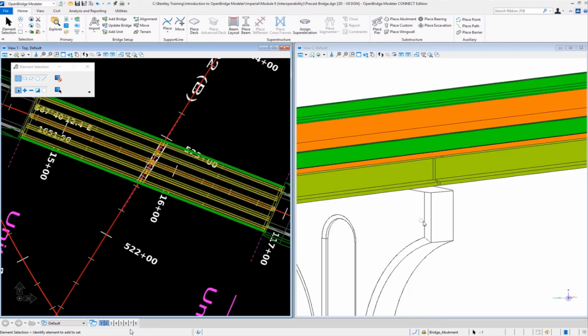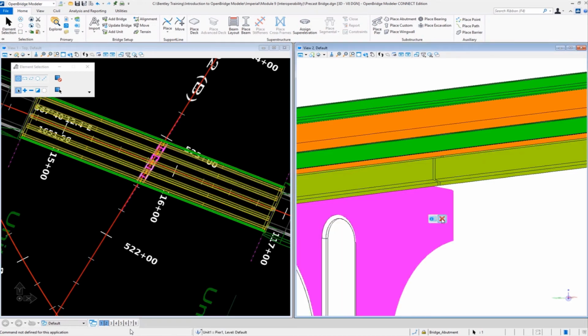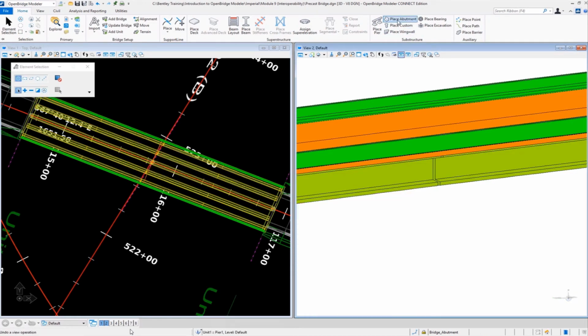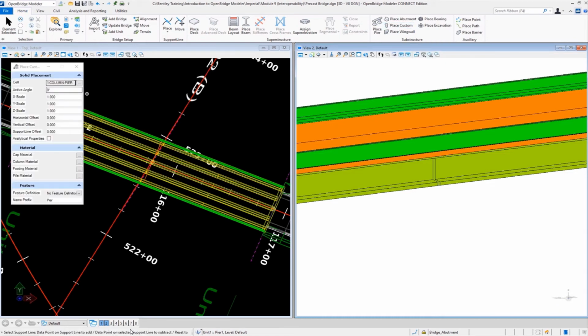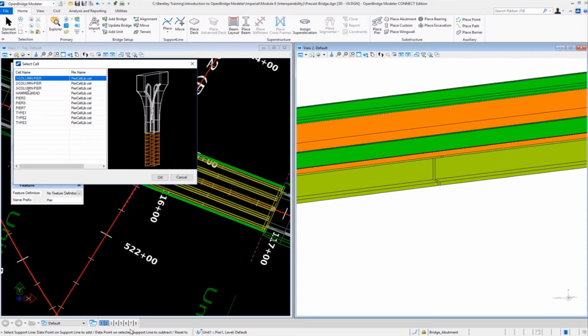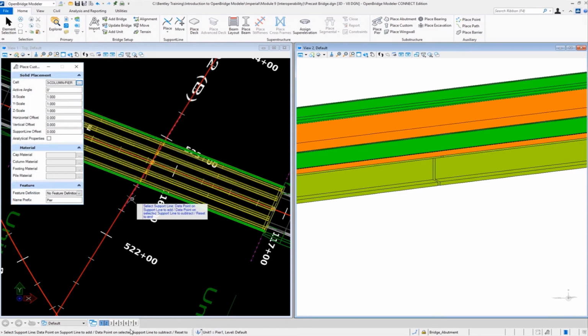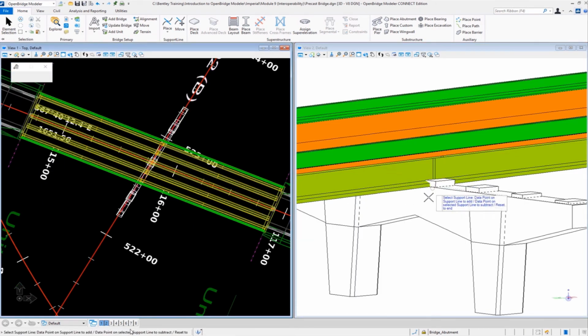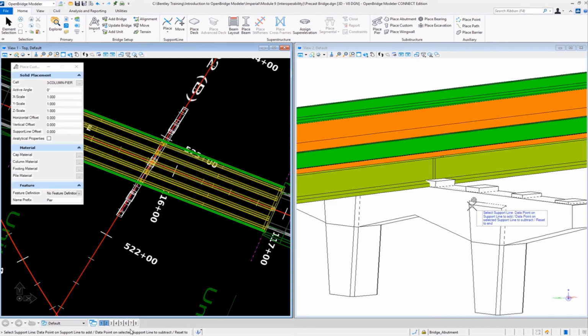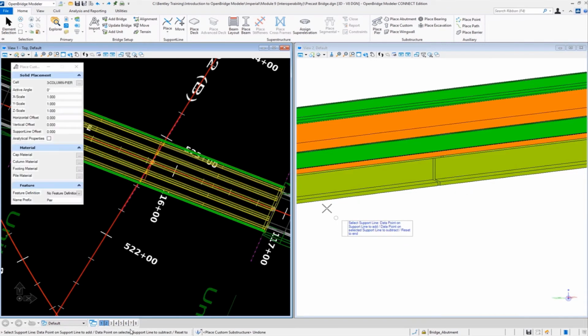I mean, you have to redo it every time, right? So if the cap moves or the bridge moves, well, you have to place the pier again. So it's not functionally working or reacting parametrically. It's more like snapping a cell there. And especially here, oh, this is too wide, I need to adjust the beam. So in this case, as you create the cell, you have to recreate a cell just for that bridge, right? So that's a custom pier right now.